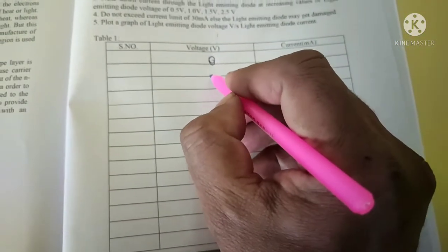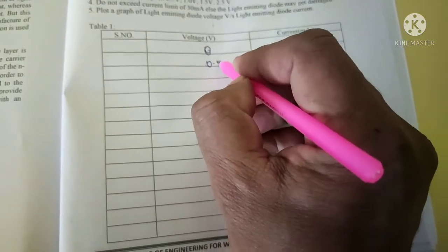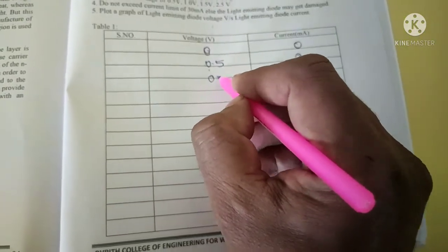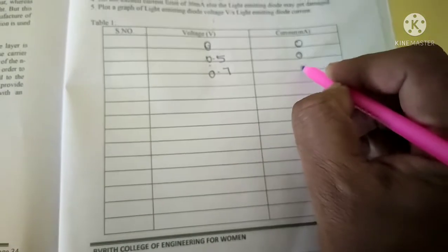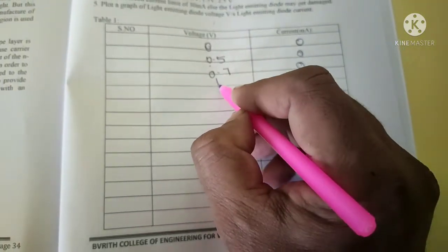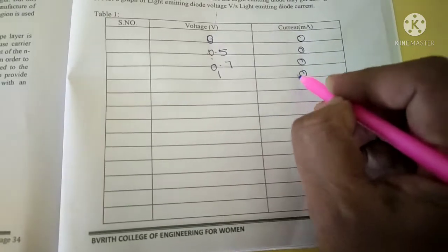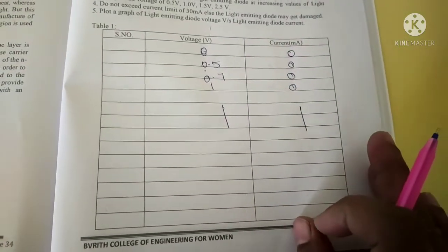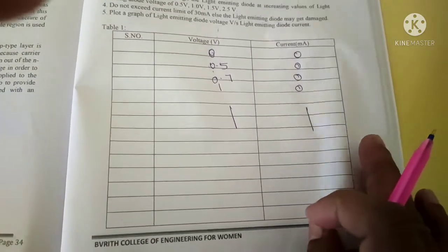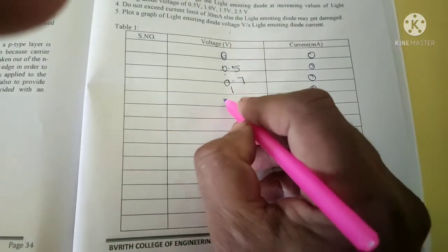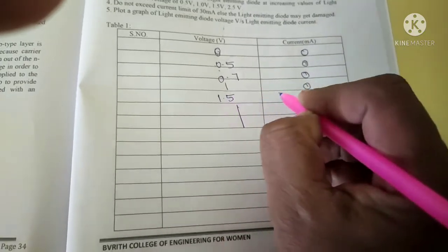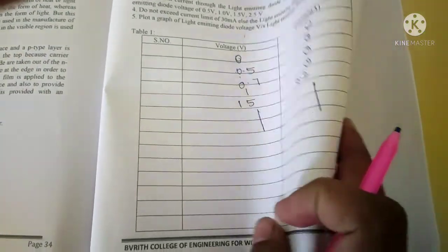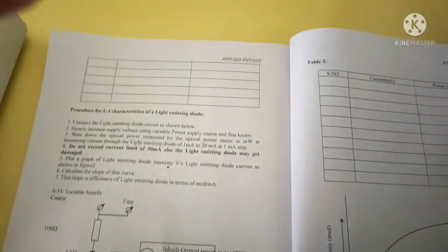For example, initially for the voltage 0, the current is 0. Even by giving 0.5 voltage, the current is 0, 0.7, 0, even 1, 0, and up to 1.5 is also showing 0 value only. But when it reaches a particular voltage, the current starts to rise. That point we should note down. Okay, so by noting down all the values,